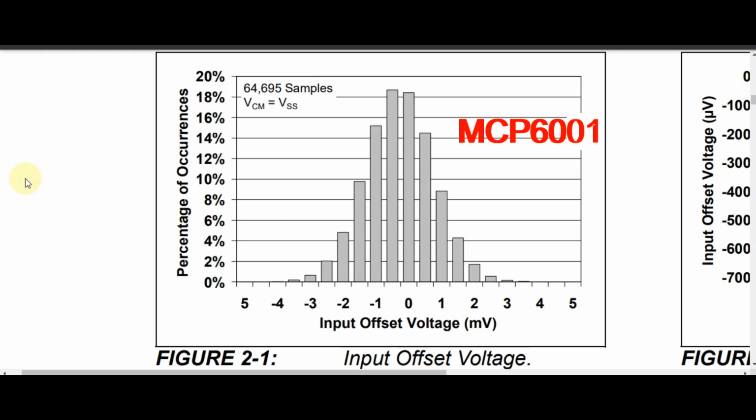So today we are going to understand one important topic from operational amplifiers, that is input offset voltage. It plays a vital role in Opamp circuit design. This input offset voltage is very critical in analog circuit design where the Opamp is being used. So we'll see in the data sheet how it is defined, and how we can understand this chart.